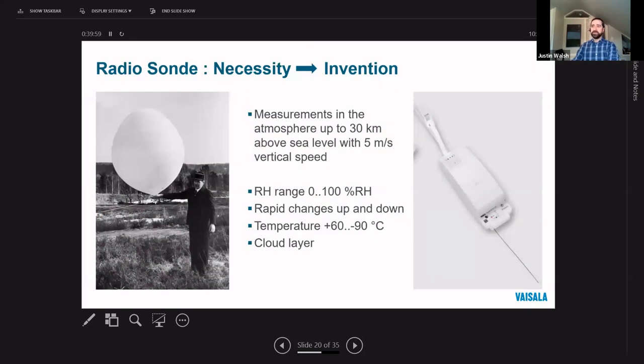A case in point is the radiosonde, or the weather balloon. The history of Vaisala is built on a radiosonde application, as Professor Vilho Vaisala, pictured here, founded the company in the 1940s after developing the first commercially viable radiosonde. A radiosonde measures the temperature, pressure, humidity, and the wind profile of the atmosphere, and then transmits the information to the ground for meteorological forecasts. They first used a hair hygrometer connected to a capacitor for the humidity measurement.